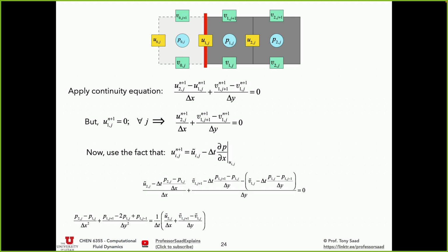Well, in fact, this equation, if you compare it to our Poisson equation, it's the same as the Poisson equation for the pressure, except that at the boundary, we eliminated some terms on the pressure. How did we eliminate them? Essentially enforcing dp/dx equals 0 on the pressure at the wall boundary, because we know the velocity. But this is a stronger statement of that derivation, right? Because we started with the continuity, we eliminated the 0 velocity, we did this assumption and derived all of this.